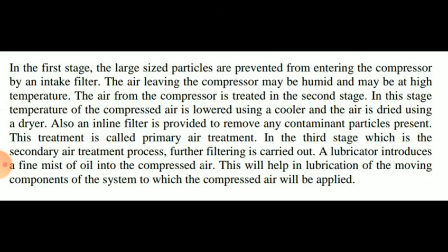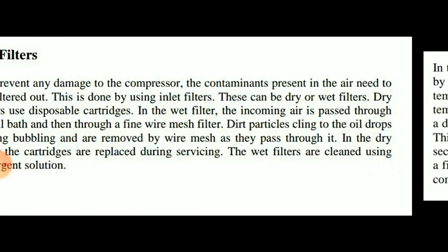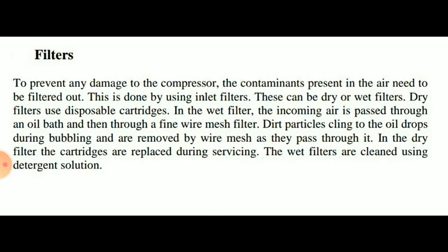So in the third stage, which is the secondary air treatment process, further filtering is carried out. A lubricator introduces a fine mist of oil into the compressed air. So this will help in lubrication of the moving components of the system, to which the compressed air will be applied. Then filters, we will see the filters.